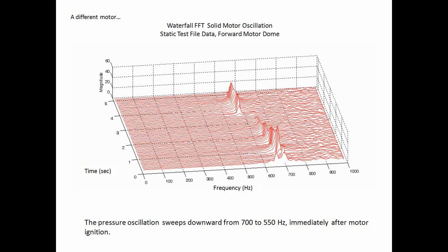So during this static fire test, we had the opportunity to collect some accelerometer data. And this was on the forward dome of this particular motor, which, by the way, is not a very good place to mount avionics components, but for a variety of reasons, sometimes we're forced to do that. Maybe there's a thrust termination charge, for example, for the flight termination system.